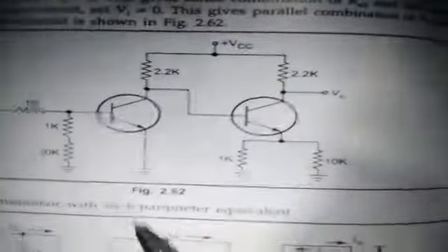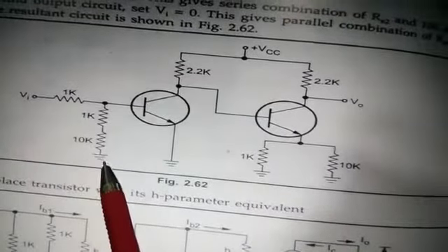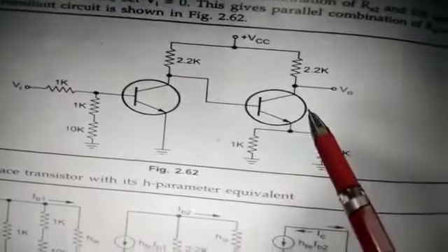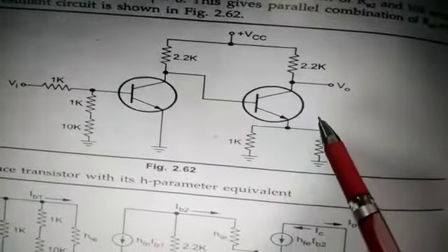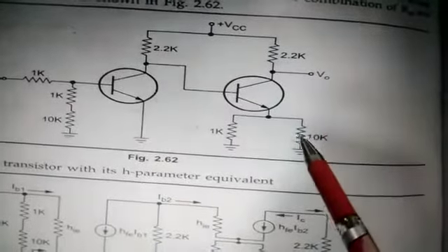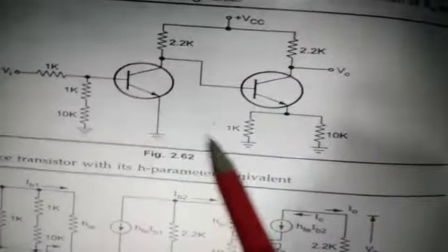So you can see this equivalent diagram. From this output we have taken the feedback to the input here. This is fed in shunt, therefore this is shunt. Since output current is 0 and the feedback is taken in terms of a current, this is the current shunt topology, or current shunt feedback.